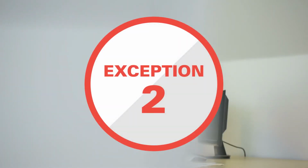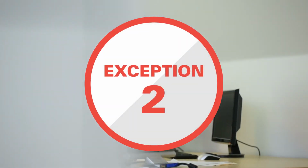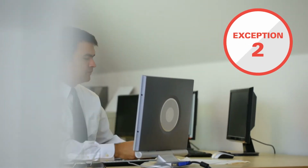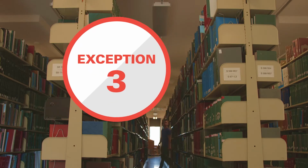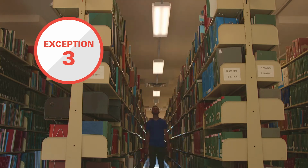Also, an area enclosed by ceiling height partitions that has only one luminaire with no more than 2 lamps does not need to meet the multi-level lighting control requirements. Lastly, areas where full or partial off occupancy sensors are required under the energy standards are also not required to comply with the multi-level lighting control provisions.